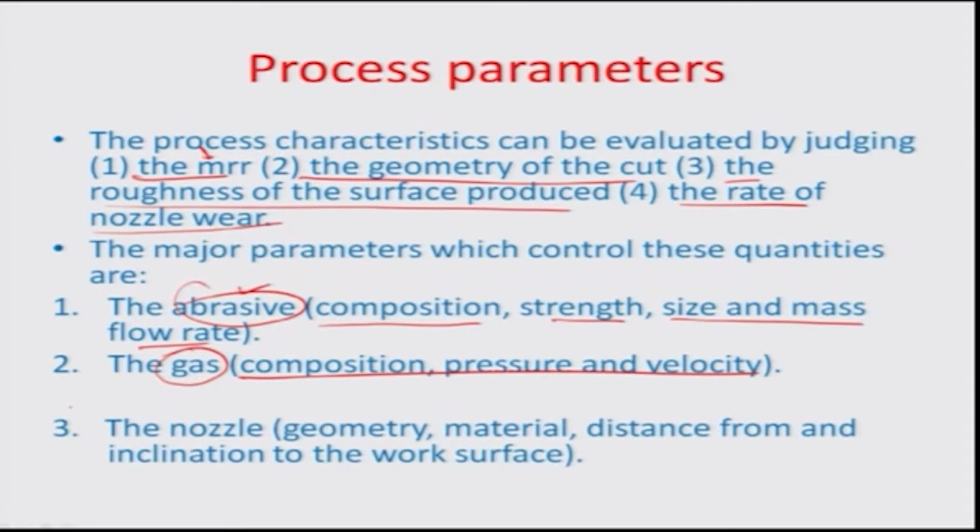Also there is a good relation between the nozzle geometry, which matters a lot to generate the overall shape and size of the cut or even the surface roughness, the MRR, and things like distance from and inclination of the workpiece with respect to the nozzle is also a very important property along with the nozzle material for determining some of these process characteristics.